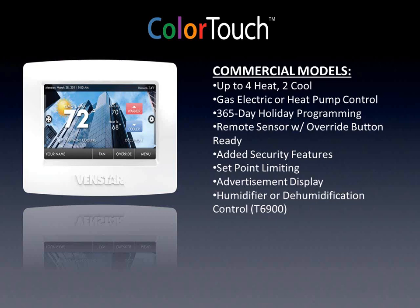It can support a remote temperature sensor, so if you want to put the stat in a restaurant in the manager's office and have a little tiny sensor out on the wall that nobody can touch out in the space in the dining room, you can do that kind of thing. There's also the ability to lock the screen out, so if you do want to put it in the occupied space, people can touch the screen all they want and it's not going to do anything. You can lock them out that way.